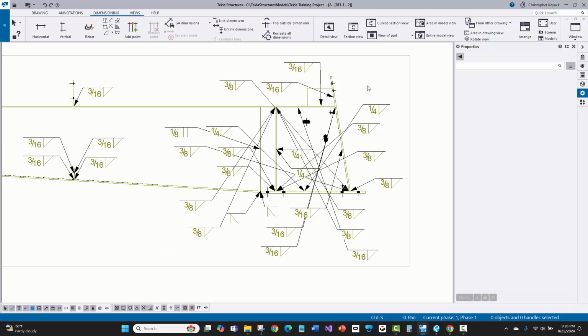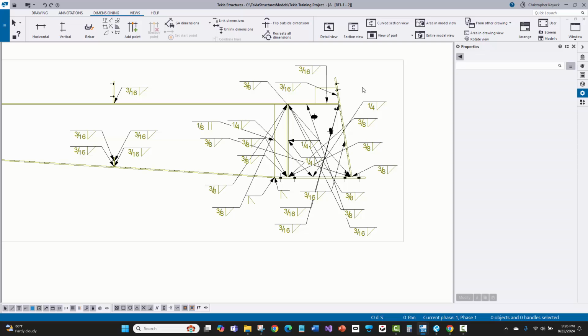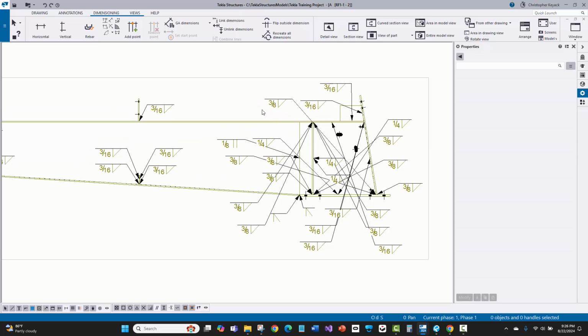So I tell people that, hey, still use your weld standards, but we're just going to try to get the welds in the Tekla model to match those weld standards. And then you'll still have the same procedure like you have with the weld standards, and don't show a ton of welds on the shop drawings, but we'll have the correct welds in the model and coming through DS Weld from MBS into Tekla to match as much as possible those weld standards, so that way the AGT machine is doing everything correctly.